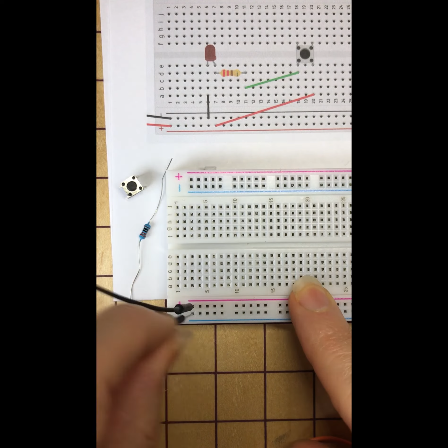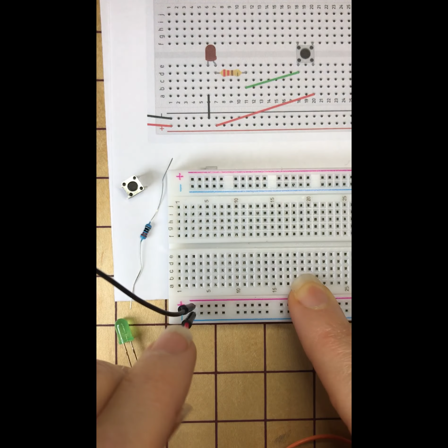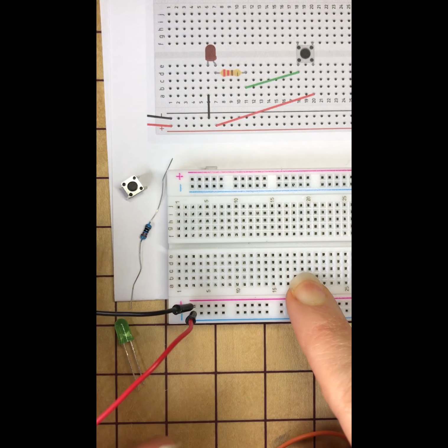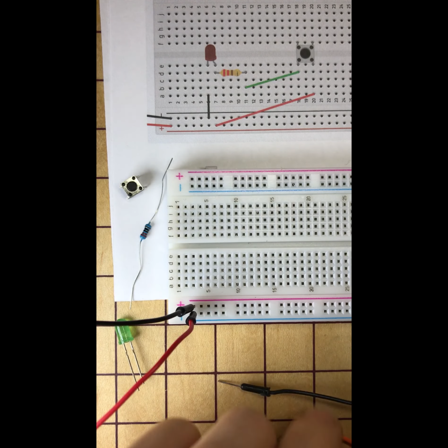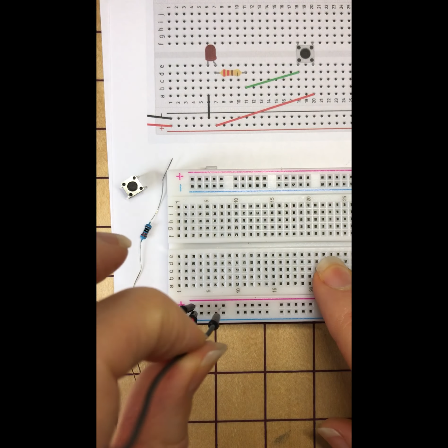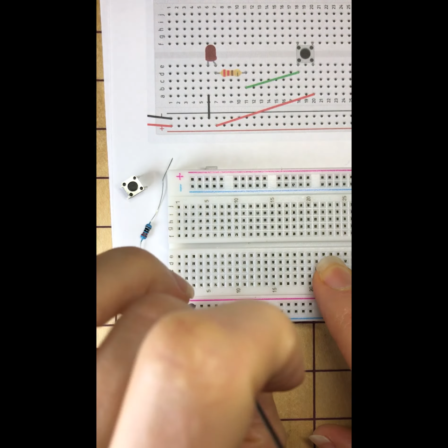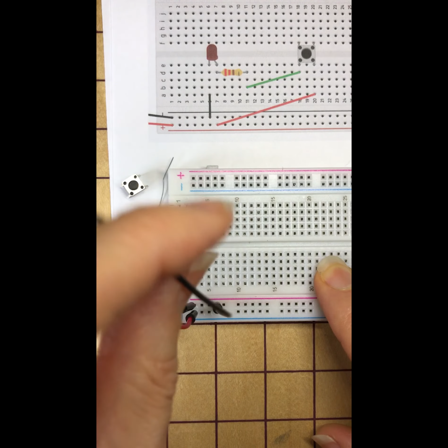And so I'm going to go ahead and build this just like it is on the diagram in Tinkercad, with the bottom row being the positive power red and the top row being the ground black negative power. And then I'm going to bring that power up to the breadboard into a row, which on my diagram is row 6.